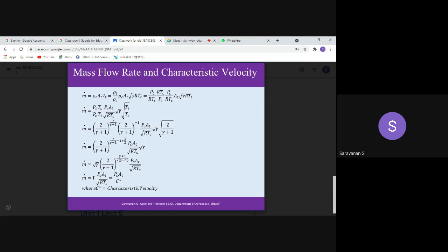So using that kind of isentropic relation, you have to be careful with the gamma minus 1 and all. If we go for the reciprocal, whether it is P naught by PC or PC by P naught or PT by P naught, we have a different component. So go and check thermodynamics, isentropic flow through a nozzle, one more time.